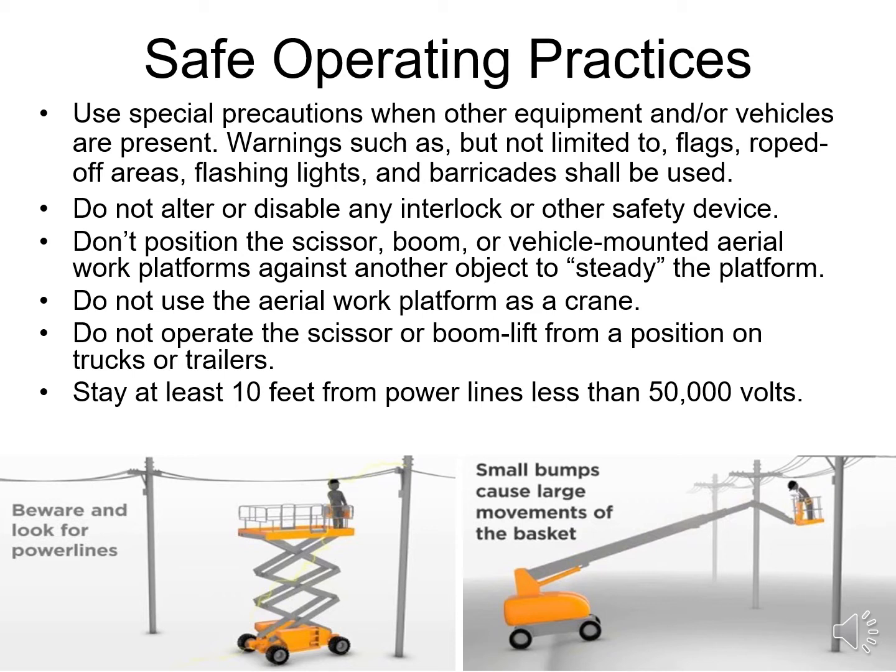Don't position the scissor, boom, or vehicle aerial work platforms against another object to steady the platform. Do not use the aerial work platform as a crane. Do not operate the scissor or boom lift from a position on trucks or trailers. Stay at least 10 feet from power lines less than 50,000 volts.